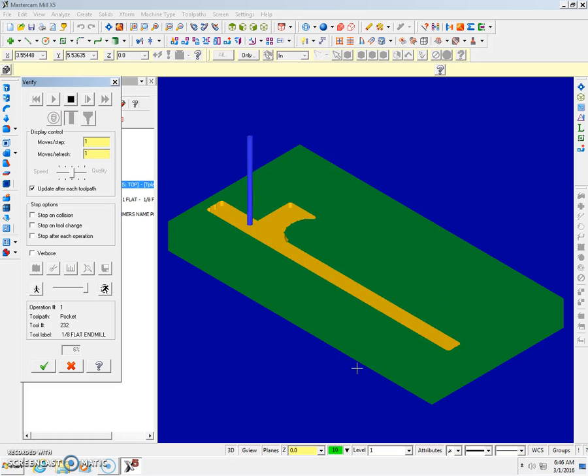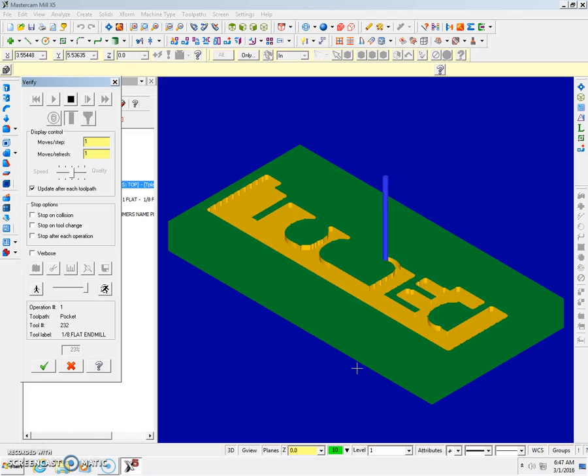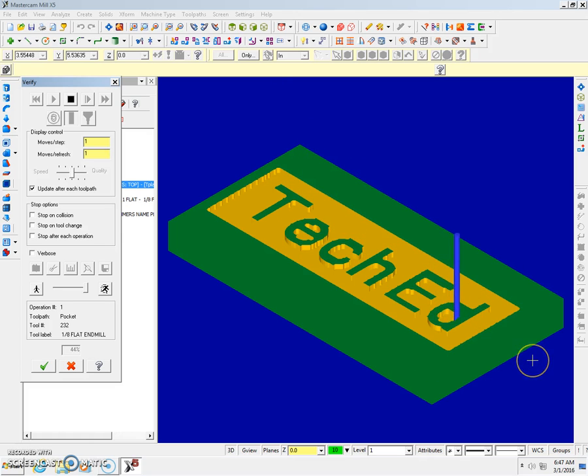It's going to take a little bit of time in order to cut your part out. This rendering, what it's doing right now, is actually the same way that the CNC mill is going to cut your part out. After this finishes, you want your teacher to check your part, to make sure that it looks good and you have your donuts cut out inside the E, inside the D. If not, we'll have to go back and change them. It's also going to do a final cut to trim up to make sure everything looks nice and smooth around all the curves, edges, and flats.